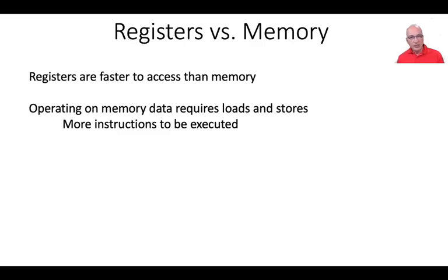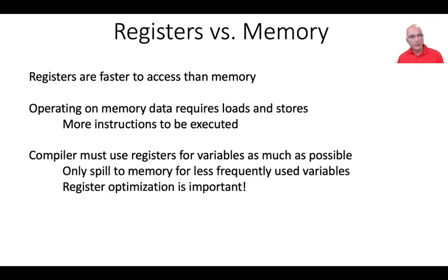In any architecture like RISC-V, where it's impossible to do an operation with memory, you cannot add to a value that's in memory. You have to first load the value from memory, perform the addition, and then if you want the value to be somewhere in memory, you need to store it back. That's called a load-store architecture, because you always have to do loads prior to the operations that you want to execute, and then after you obtain the result, you have to do stores to store back into memory.